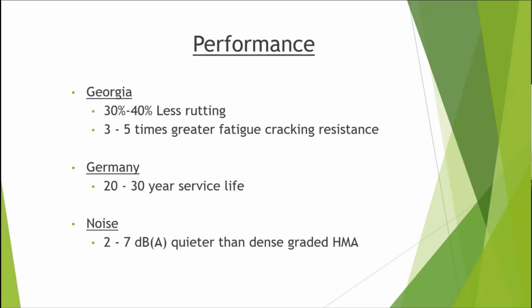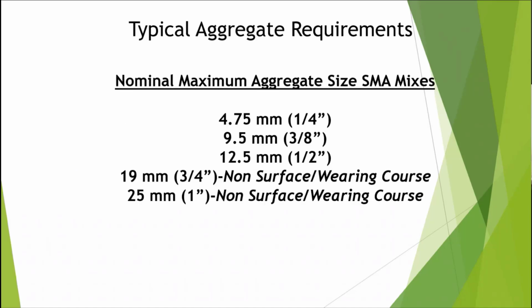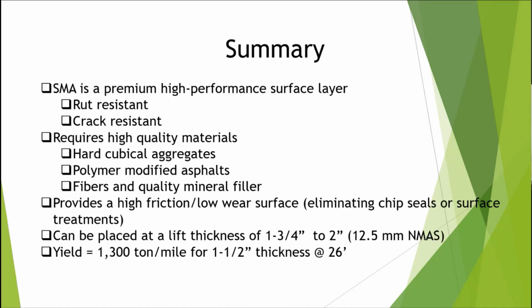Interesting part is the bottom one, because it looks open textured when you place it, but it's still impermeable. But that'll absorb sound as well. So research has shown it can drop traffic noise, tire noise, by 2 to 7 decibels. You can do it in different nominal maximum aggregate sizes.